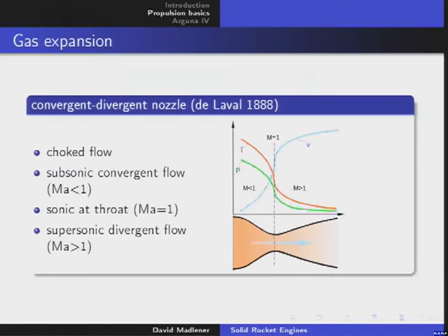And what happens is that very hot gas comes from the burning chamber, goes into the converging region, accelerates, and then at this point, at the throat, reaches exactly Mach 1. But Mach 1 for the local temperature. And as the temperature is very high, Mach 1 can be 1 kilometer per second or more. And when it leaves this throat, it even accelerates more. So it can achieve multiples of Mach. And you can get exhaust velocities up to 4.5 kilometers per second with a simple chemical device, or even 10 kilometers per second with a nuclear engine.